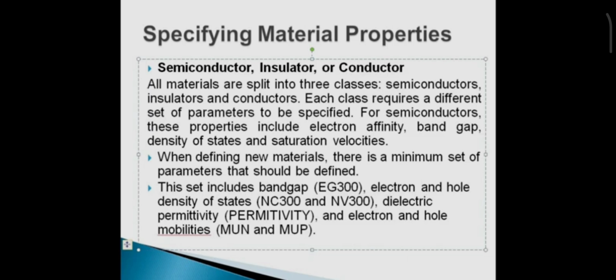If you are not using the material statement and the material you specified in the Atlas code is already present in the Atlas manual, then it can take the default value. If you want to change this default value, you have to introduce the material statement. The material statement allows you to specify your own value for these basic parameters. Next slide please.